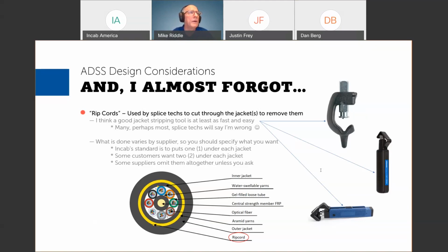And if you had a reason to be concerned about something happening, you could even do a little bit of belt and suspenders by taking a dielectric armored cable like that and putting it in a conduit and putting it underground. So basically, the way you avoid electrical issues in underground circuits is get rid of the metal.